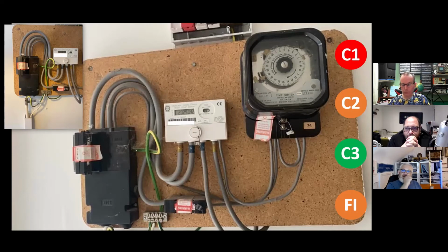So there is a lot in documents. If you go back to 1992 even, the London, Eastern or Southern Electricity Boards produced these PME guides, the first of their kind. Anything that was on a branch, which is like a radial off a feeder cable in the street, anything that was end of line that had more than 4 homes on it, if it was PME, you would put an earth electrode at the end of line in case of a lost or broken PEN. And that's what that is. That's actually an earth conductor down to an electrode at the source of supply. But everyone assumes it's TT.